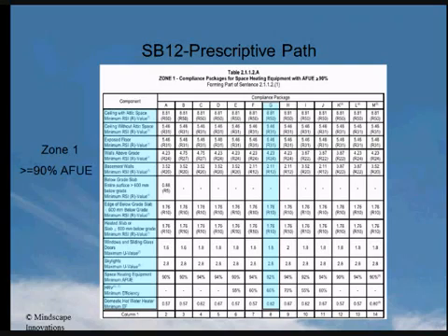For package G, any ceiling with an attic space must install a nominal R value of 50, with all packages having a minimum R value at the location directly above attic hatches and the inner surfaces of exterior walls of R20. The ceiling without an attic space has a minimum of R31, which is the same as that required of an exposed floor. Walls above grade are a bit more complicated, and they include walkout basement walls containing the door in this package must be R24.